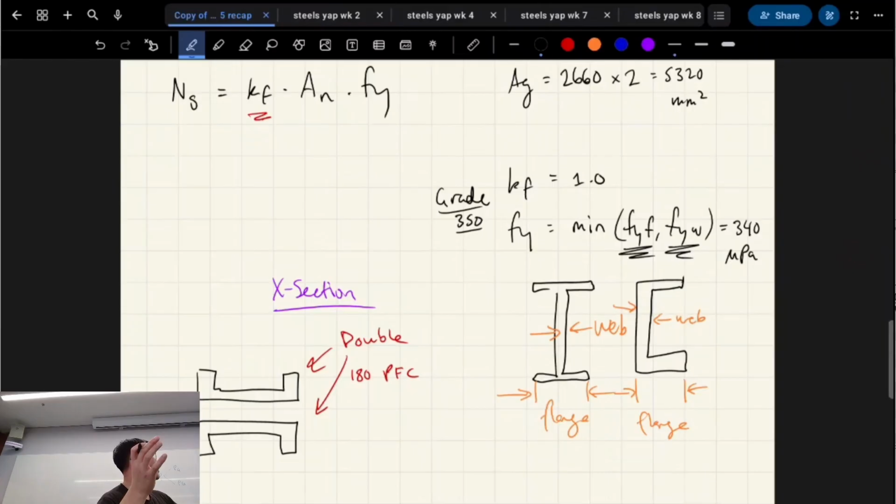You're going to find that the thicker your section gets, the lower its yield strength gets. So imagine you pour a meter by a meter by a meter, so like 1 meter cubed of molten steel, right? And you just let it cool, and you're trying to use this structurally. Do you reckon that that's all going to evenly be cooled?